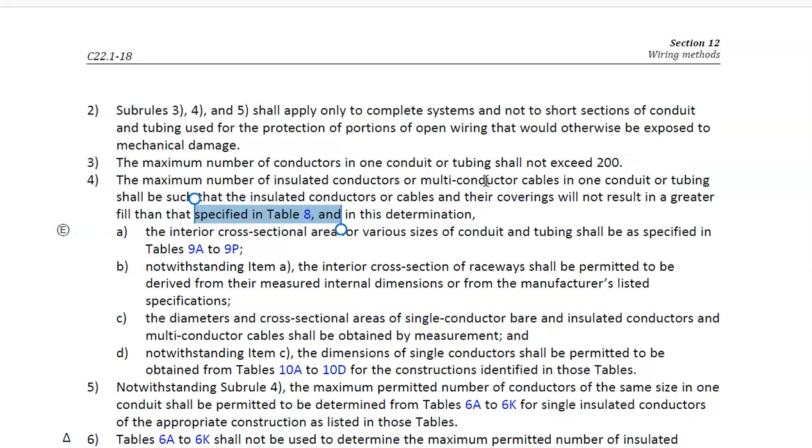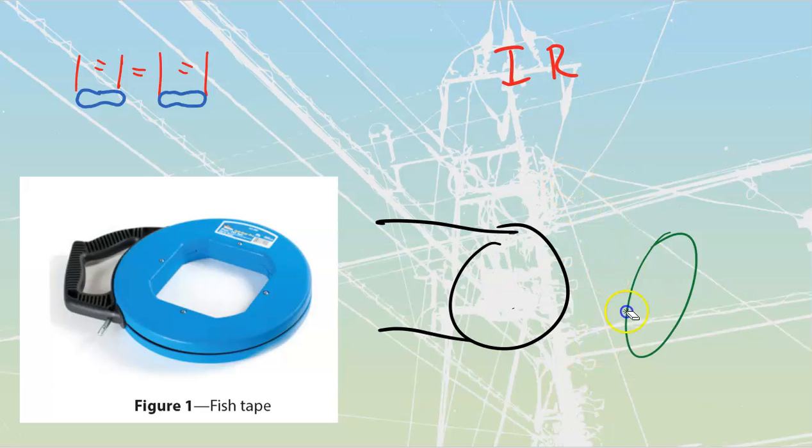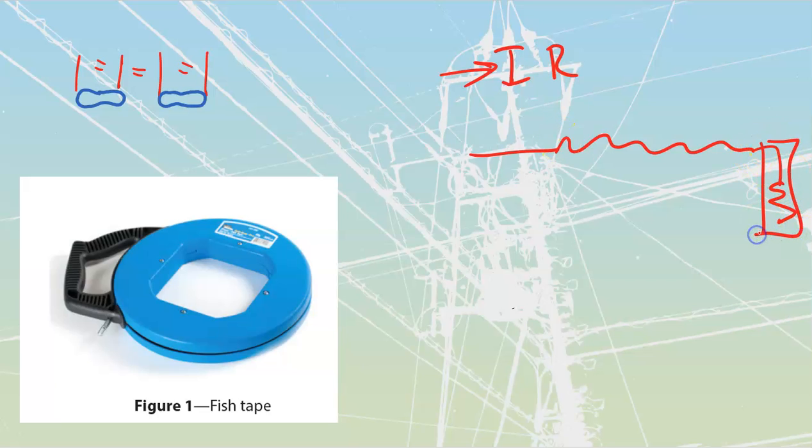All right, voltage drop. Voltage drop is commonly going to be referred to as my IR drop. You'll hear it. People will say, the IR drop of this, etc. Anytime that we're dealing with an IR drop, we're talking about how much current, amps, am I putting through that conductor over top of the length of the conductor, which is acting like a big long resistance, and therefore how many volts am I losing before I get to my actual load at the far end. It can be a significant amount. Everybody's had that, where you're getting low volts on something because the cable run was just so incredibly long.